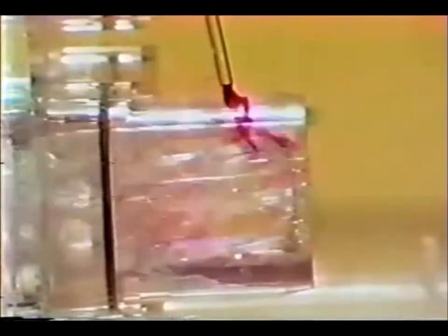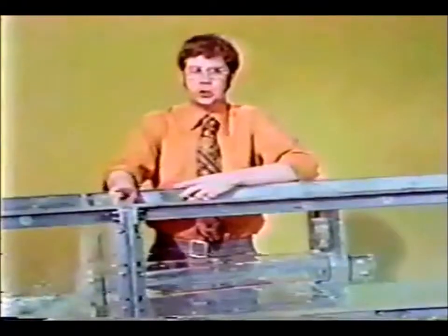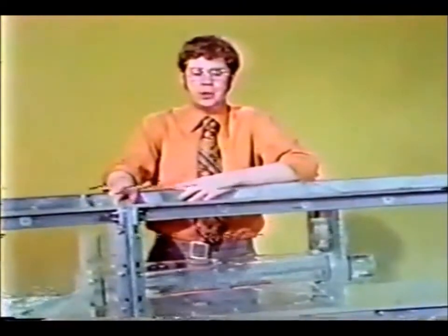With the aid of some dye, you can see the streamlines approaching the intake. This is because of the severe contraction and separation of the flow at the entrance. The water has to make about a 180-degree turn, and as it does, it breaks away from the leading edge and contracts. The contraction is very severe, and only a portion of the barrel area is being utilized.